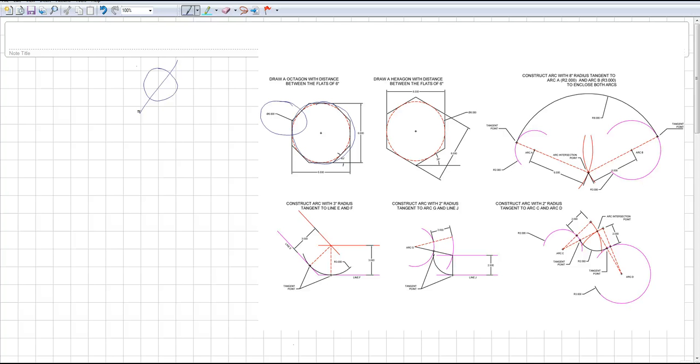Okay, we don't have a symbol for the radius here. Oh, right here. Okay, so the symbol of the radius is drawn just as R 3.0. Diameter is drawn as diameter 6.0 for the same exact circle. So what you see is the diameter is twice the size of the radius.